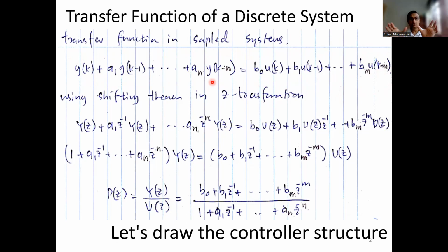And they are related through a certain set of coefficients like B0, B1 to Bm, and A1, A2 up to An, right? So this is generally true for any system in discrete time. So these A's and B's represent the dynamics, in the sense of how these variables are related to each other. That's essentially what we call dynamics of a plant, okay?